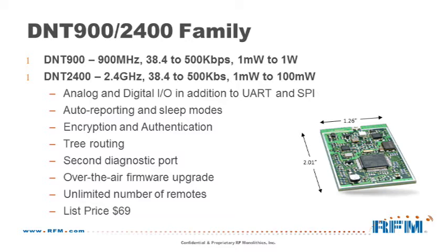Then we have auto reporting and sleep modes. So you can actually put the radio to sleep, which puts it into a lower power consumption. But then you can also configure it, on either a time or interrupt or analog voltage basis, to wake up and transmit its data.